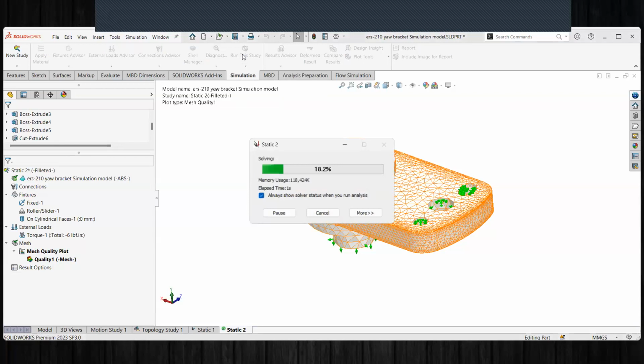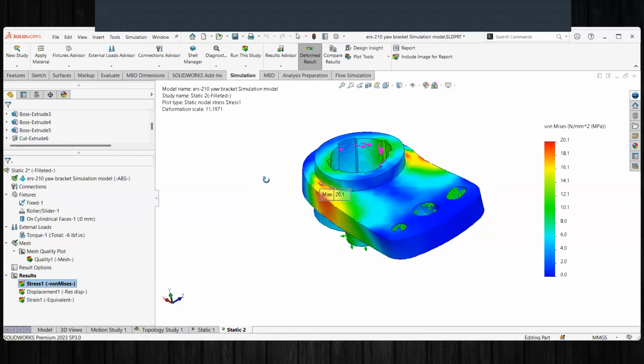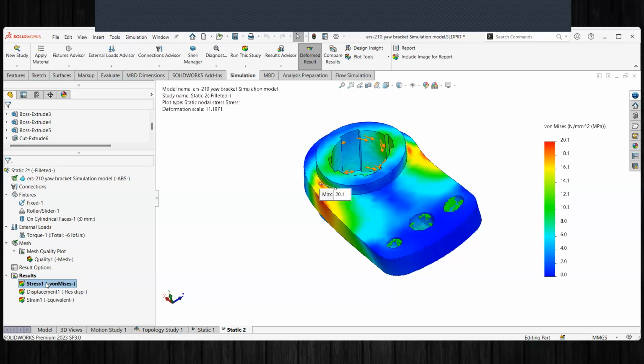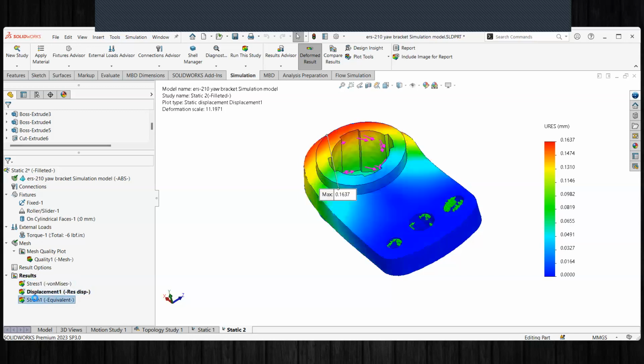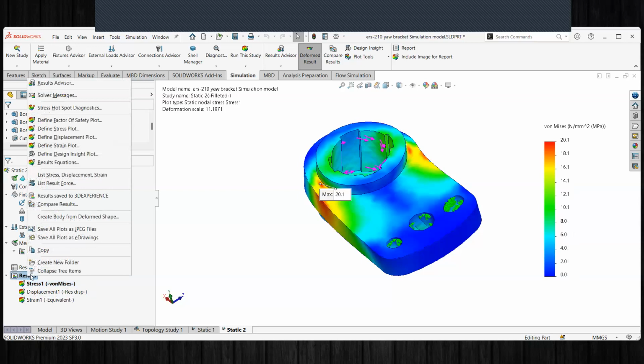Perfect. I just want to touch on two main things before we do another topic here to round off and close the seminar for simulation. We want to show qualitative results and quantitative results. So for qualitative results, we can add as many of these plots as desired. SolidWorks Simulation will add 3 as default: stress, displacements, and strains. You can add many other types of plots. So if you're new to simulation, just go play around with it.